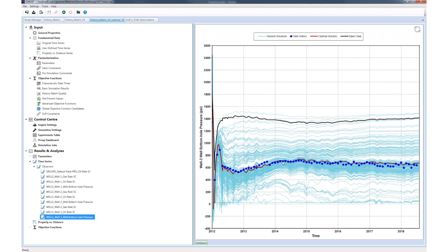Now that we have this history match, we can rerun this model with our current operating strategies and get an accurate forecast of what we can expect for the rest of the life of these wells. Another option that we have is using CMOST to set those operating constraints as parameters and let the CMOST algorithms find the most optimal strategy for us.